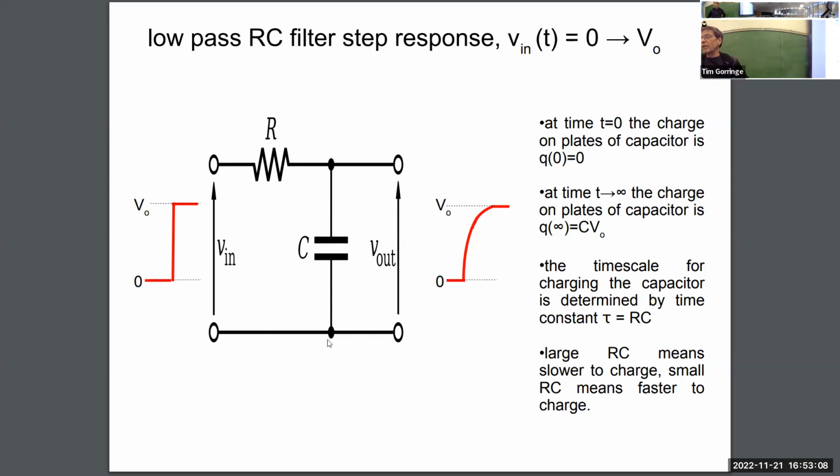So this little circuit here on the left-hand side, made of one resistor and one capacitor, is what we call a low-pass filter. So if you were to apply a signal, a voltage signal, say, between the two inputs on the left-hand side, and you were to read out the voltage signal on the right-hand side over here, what you would find with this little circuit is that low frequencies would pass through from the input to the output, so it's a low-pass filter.